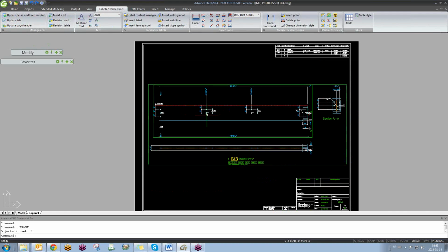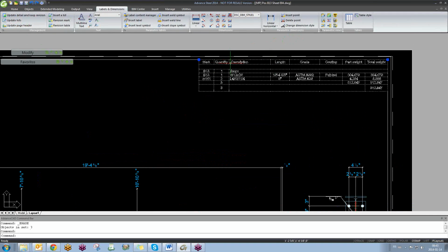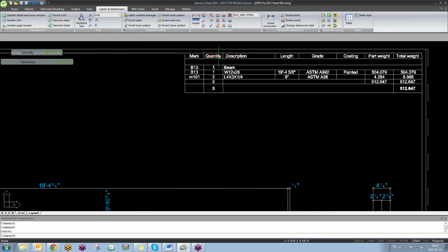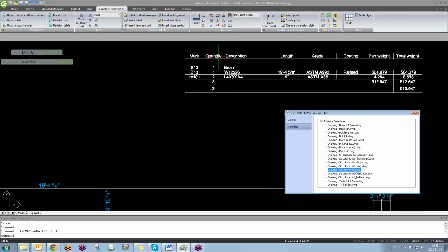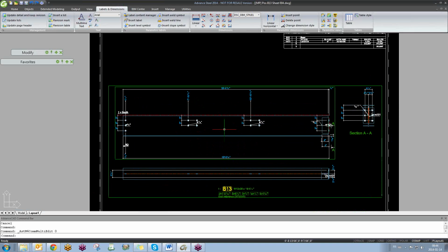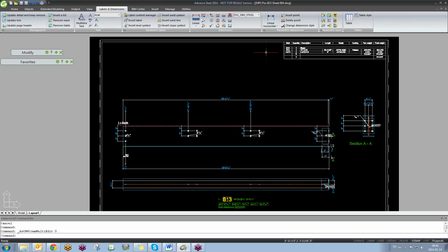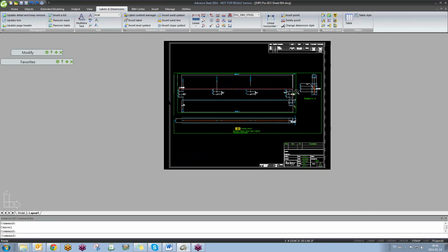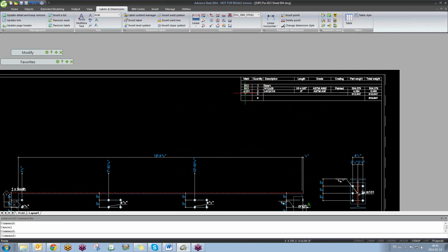By the way, guys, if you are doing your lists and you are not using this kind of list, because this one is a structured list, and instead you want just the beam list or something like that, to be by default within your drawings when you are using main parts drawings, you only have to, while creating your block, your title block, your prototypes, insert the list within the prototype.